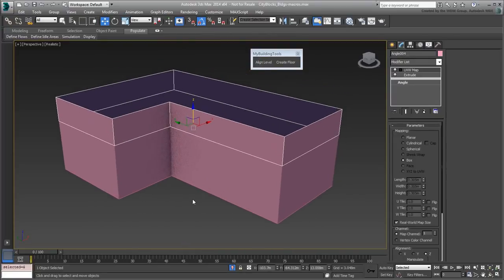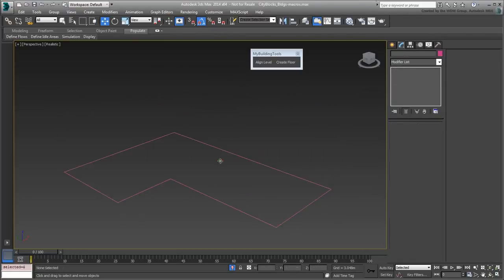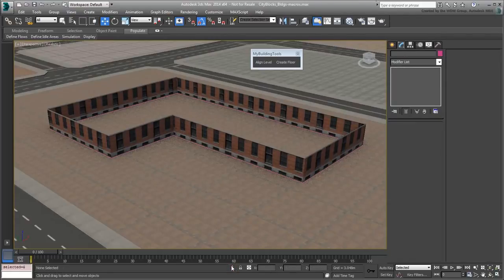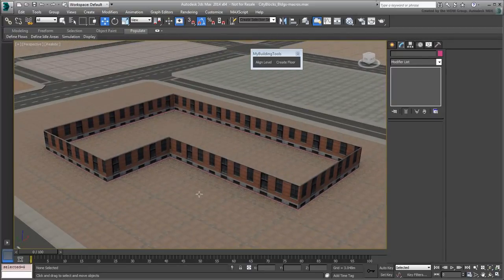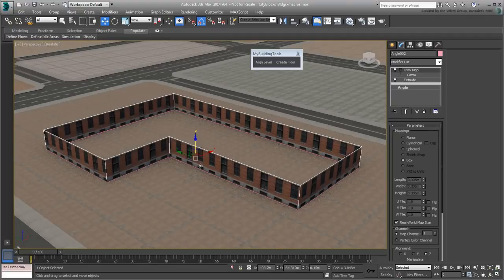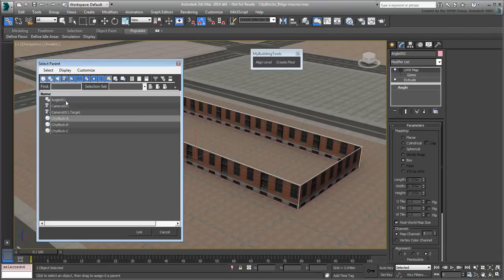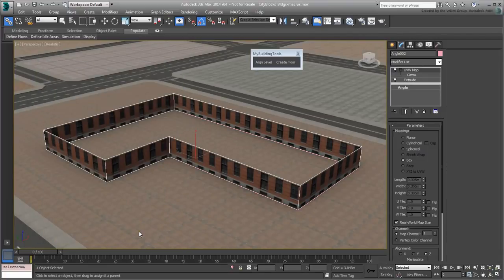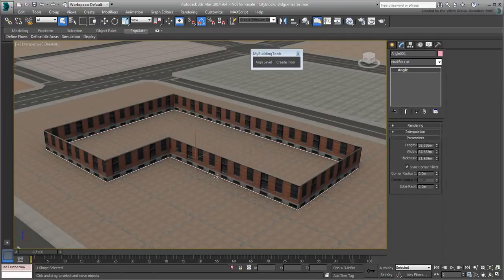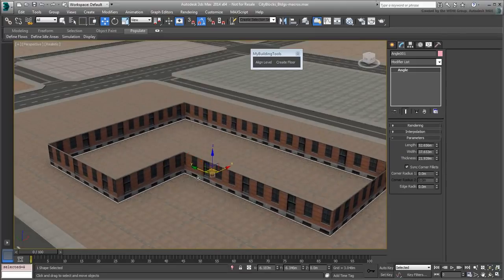With the scripts in place, remove any floors you may have created and exit Isolate mode. Use the Link tool to link the first level to the main base shape, since that level was built entirely manually. It may be easier to use the Select from Scene dialog to prevent any errors. This linking task will be automated for future floors, as the process is now built into the script you created. Save your file. In the next movie, you finalize your first low-poly building.